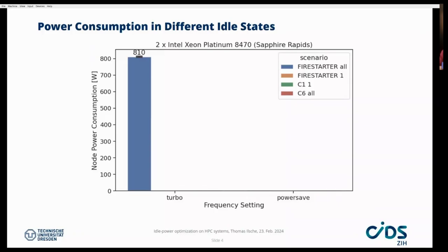That is a full operation. If we go to just a single core, so we have the same configuration, but one single core is executing the same workload, and we have over 100 idle cores on the whole system, we still use over 55% of the power budget. So we still use over 400 watts here, and this is a relatively high number compared to previous generations. So Sandy Bridge-ish generation, we only saw about 31% power usage of a single core being active,